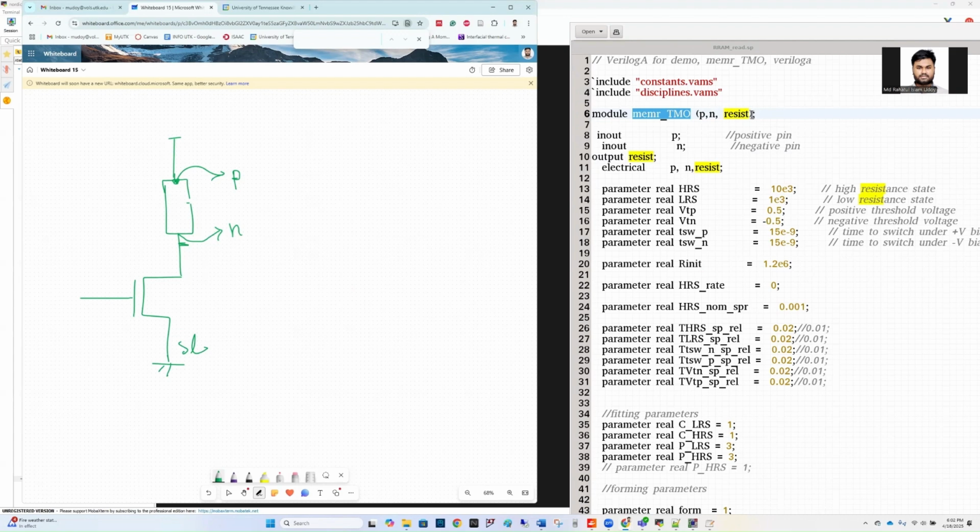The name actually suggests its function. It will show you the resistance value of this memristor. Currently the memristor we are using has a low resistance state of nearly 3K and a high resistance state of nearly 30K. If we need to observe what resistance state it is in, we can probe this terminal.